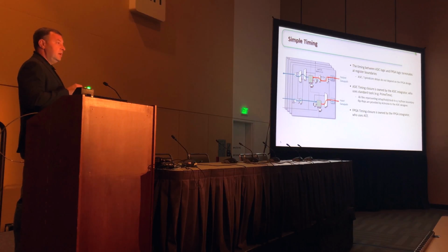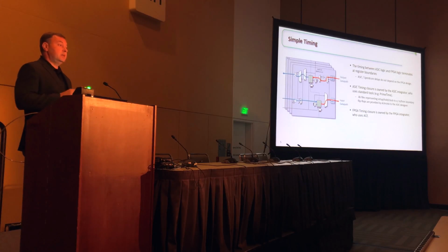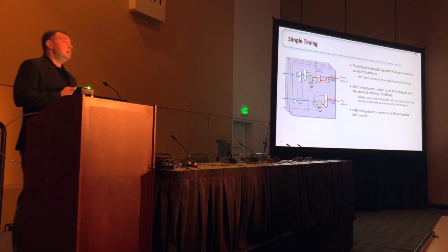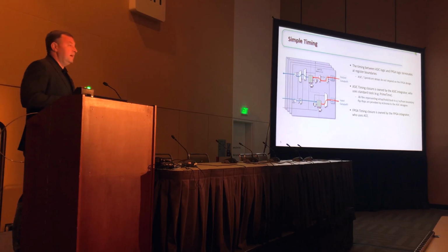He's got his output delays, and he goes through his own combinatorial logic, and then he gets to whatever flop is inside the ASIC. The FPGA designer only has to worry about the FPGA logic here, going through the output data path and setting up before this flop. So in this case, these two people, they live in different worlds. They don't really have to talk to each other.